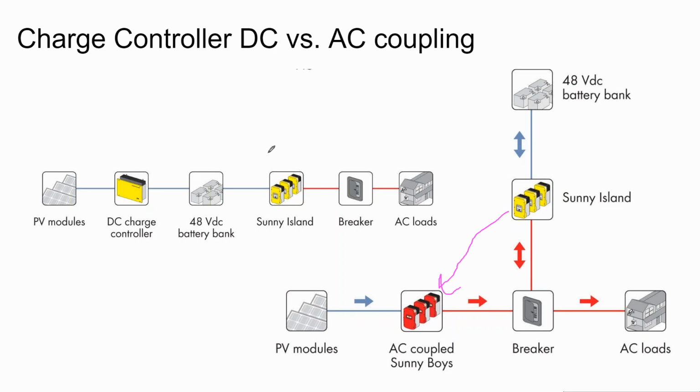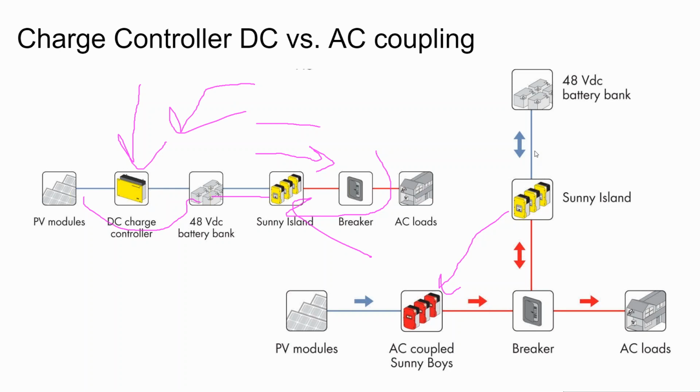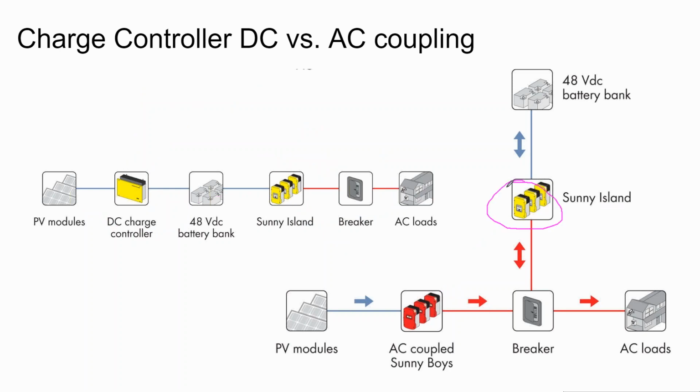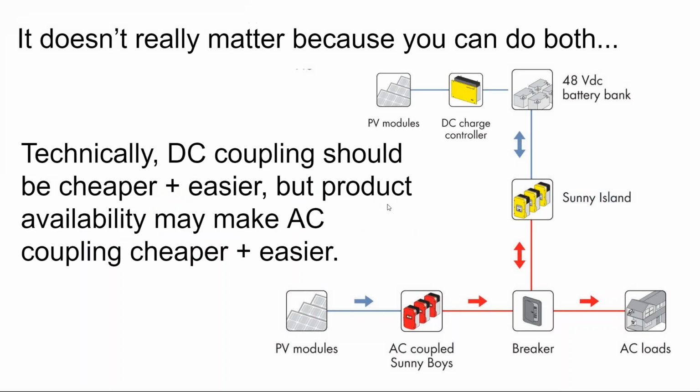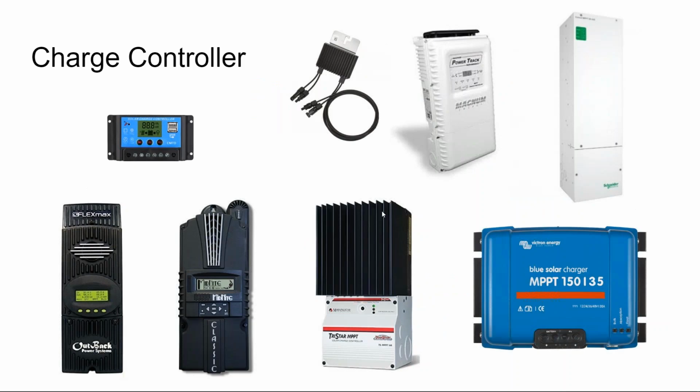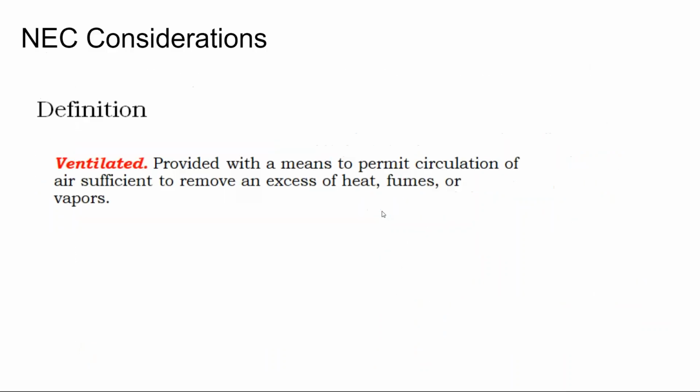I have a weird kind of battery inverter that's a one-way battery inverter, and so I have to do DC coupling in order to charge the battery up, because the battery doesn't charge from the load. The generator would have to go on this side. But like your Outback inverter, your Schneider inverter, your SMA inverter, your grid-tied battery inverters, they can charge from the grid, they can discharge into the grid. That's different than a solar inverter that is traditionally a one-way inverter.